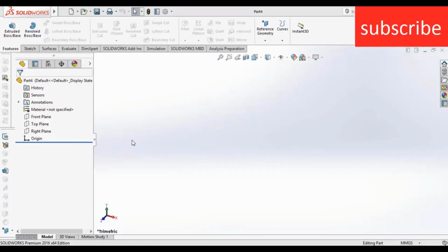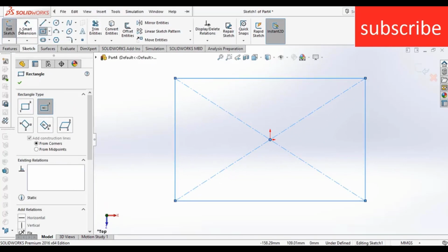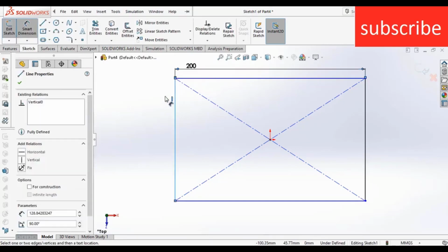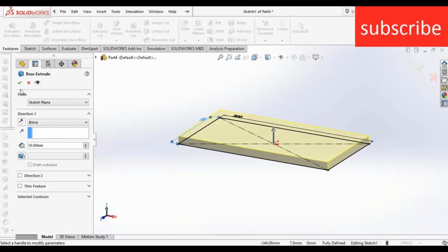Namaste guys, this is CAD Knowledge, and in this video you will learn how to do a thermal simulation in Solidworks for beginners. To do a thermal simulation, we first need a geometry. So select a plane in which I am going to first draw a sketch and my geometry. 200 by 100. These are the dimensions of our plate on which I am going to place my heat.